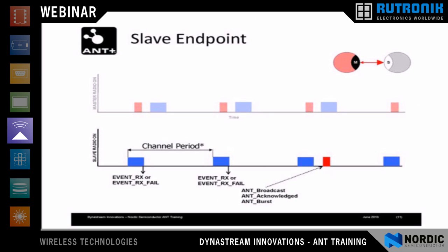So you'll see the devices line up. You'll see a broadcast and an RX and a TX messaging coming by. You'll see how the receive window aligns up with the transmit window, and then any acknowledgement sent back on the bottom line there, the red node, is lined up with a receive window on the master side.